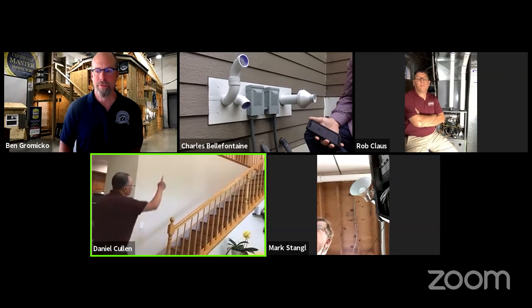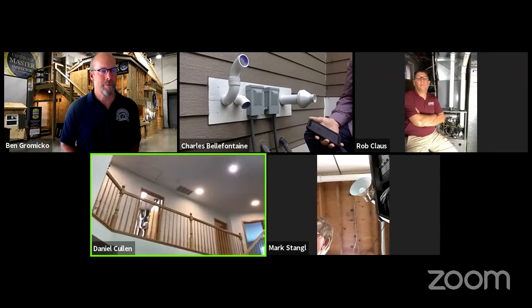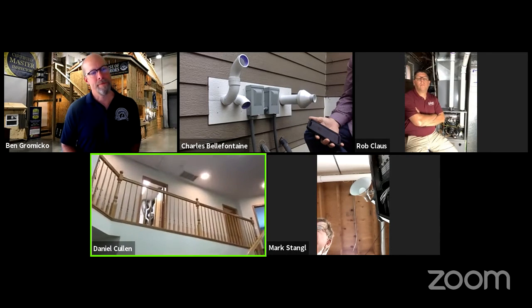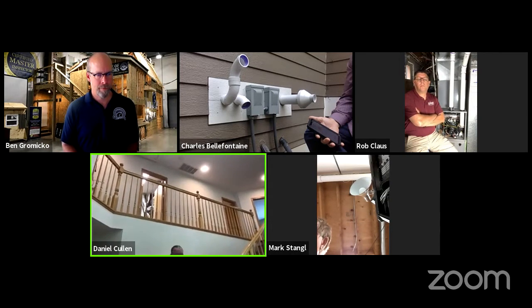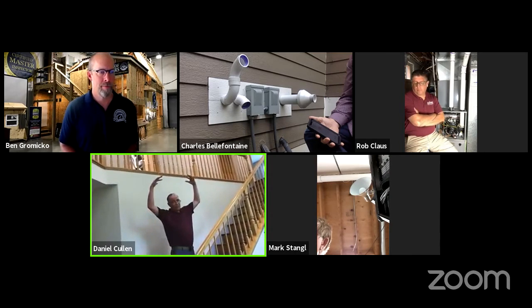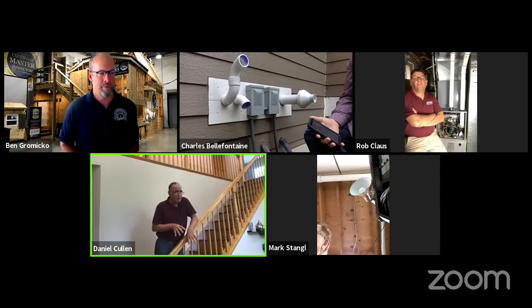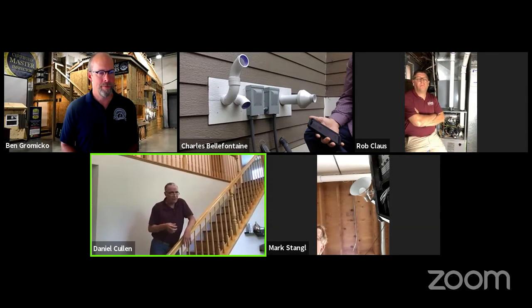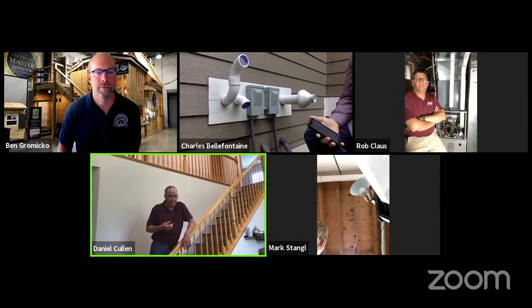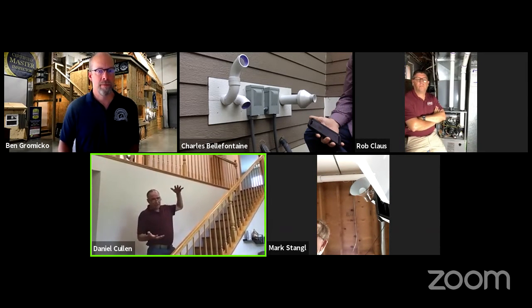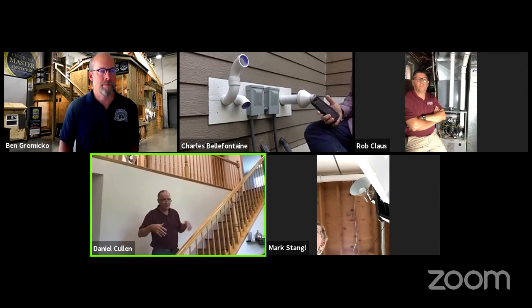Let's go upstairs. Here's our main return air up here. That's helpful in the summertime when all the warm air is up there, or in the wintertime when the convected air stays at the ceiling. However, in between cycles of heating and cooling, obviously, the air is going to stay there. And that's why more modern equipment that has a more efficient blower motor, an ECM motor, electronically commutated motor, which we can run much more frequently, can constantly destratify the air, send it back to the unit, and send it back to the supply registers. That can be very helpful.